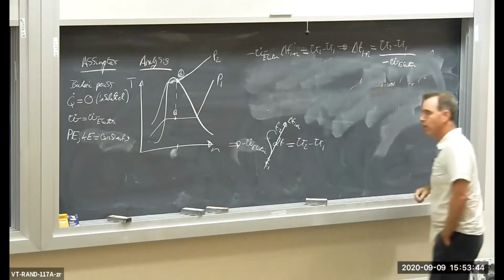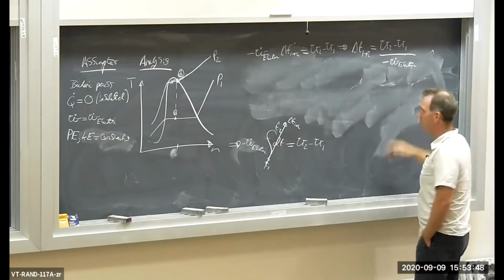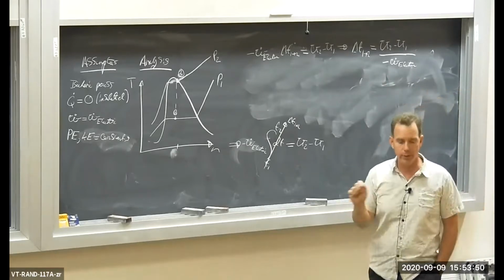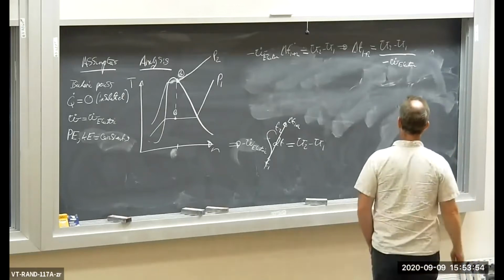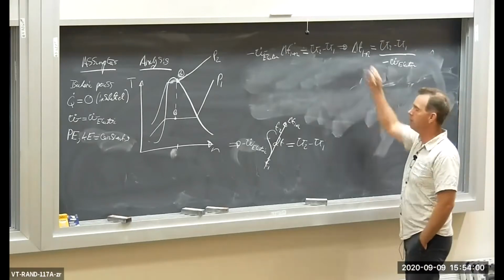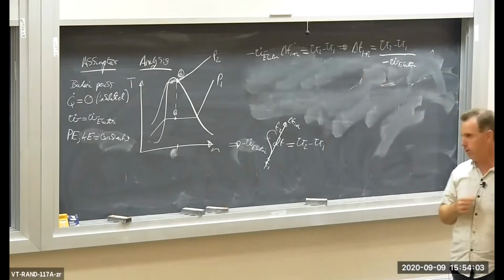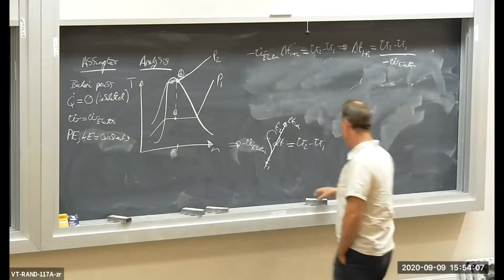If you're wondering what we're going to do about this negative sign here, remember the electric work or power is being done on the system. So this W dot electric will actually be negative voltage times current. So the negatives will cancel out and we will get a positive value for delta T. Okay, so let's see what we got.